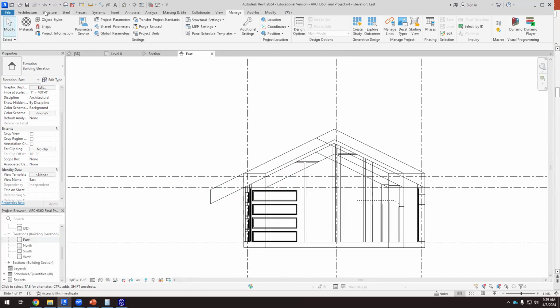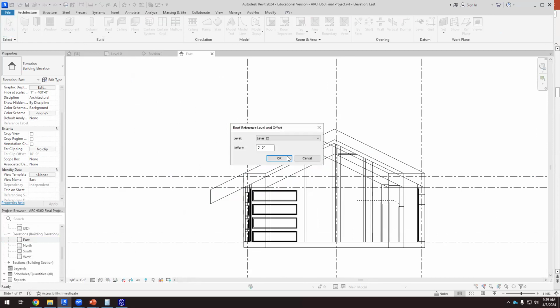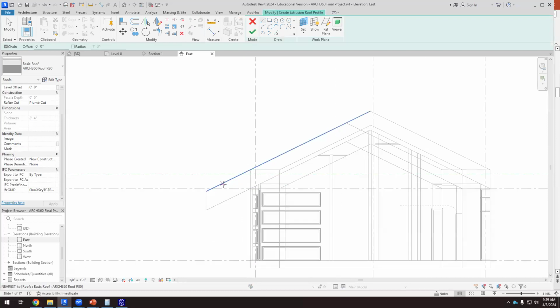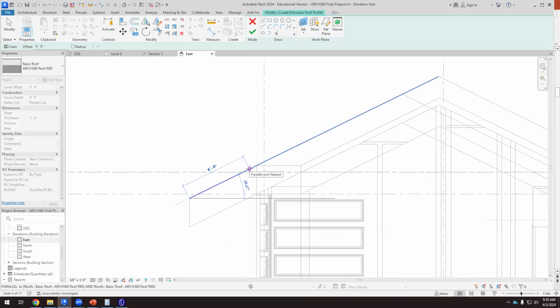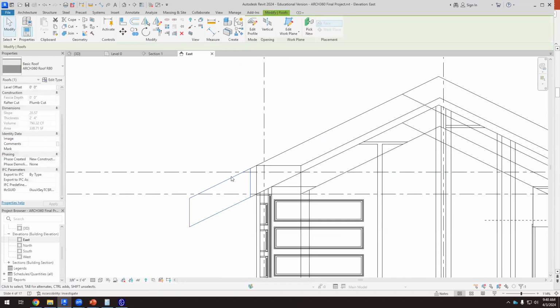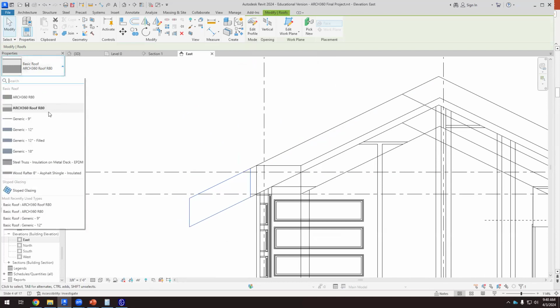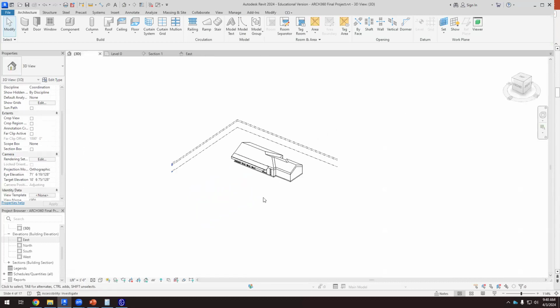So now I'm going to create a roof by extrusion. And I'm going to start here. And I don't know, usually those solar collectors, it's 3x6 or 3x7, something like that. So I can have like a 6-foot line here. I can click OK. So that's the roof, but I want something way thinner. So we have this 9-inch. Can use this. Okay. And now on the 3D view,